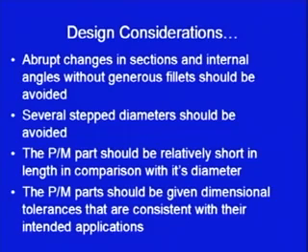Then the next design consideration is that several stepped diameters should be avoided. Why? Because a density gradient may be there; the density may not be uniform throughout the bulk of the powder metallurgy part. The powder metallurgy part should be relatively short in length in comparison with its diameter. This I will explain with the help of a diagram.